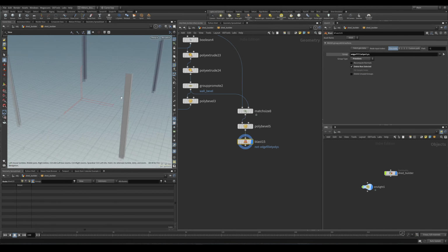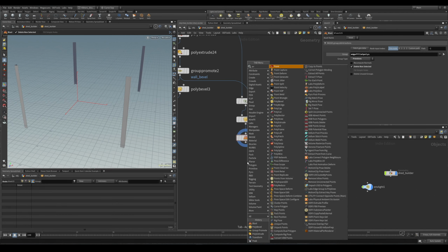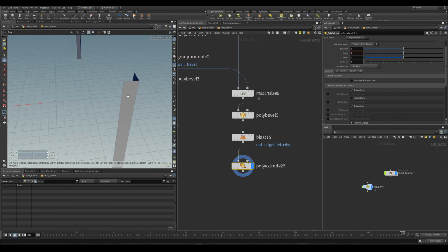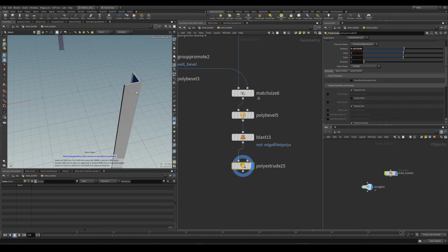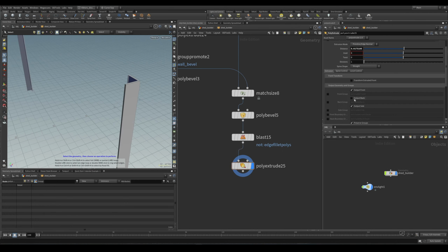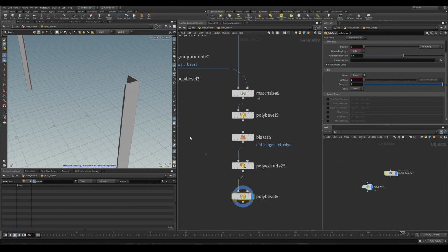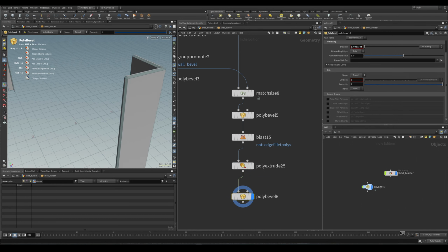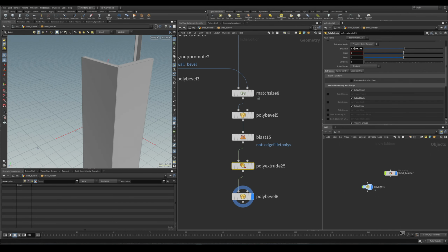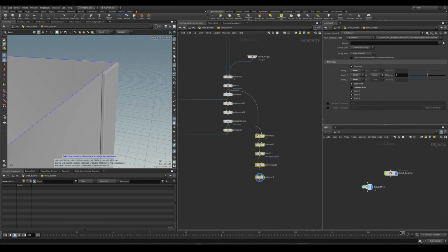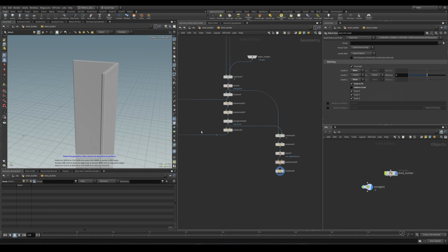You can see these are basically our trims, and we can just use a poly extrude like that. We can do it something like this, and we can also output back, and then we can extrude bevel it just a little bit amount, so we could add this bevel amount to basically the same amount that our wall has, but I think for our corner trims we should even bevel it less than.